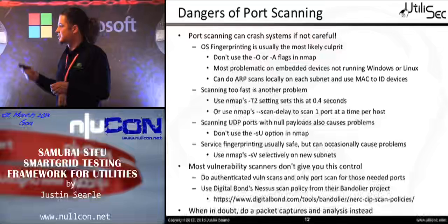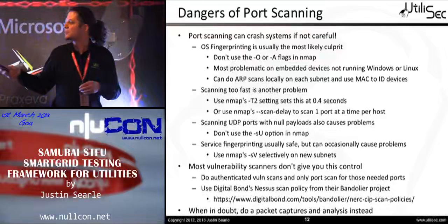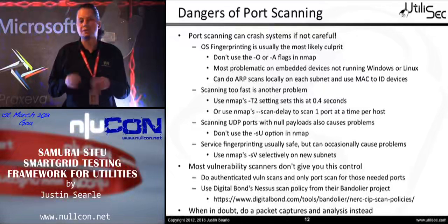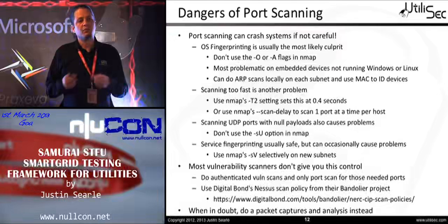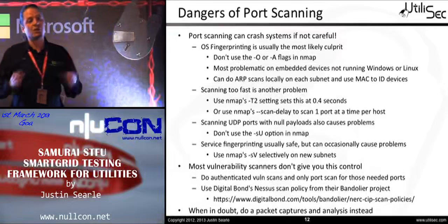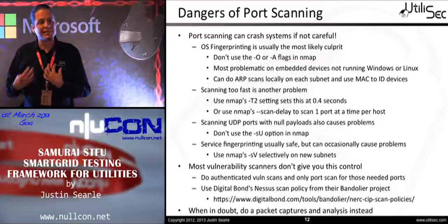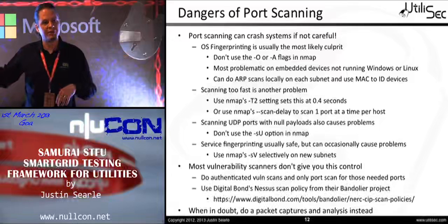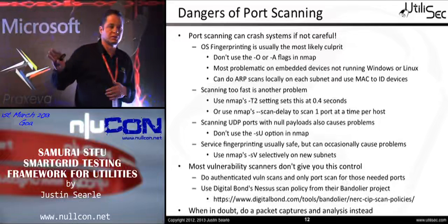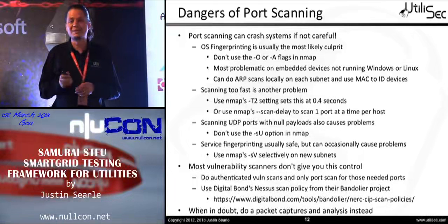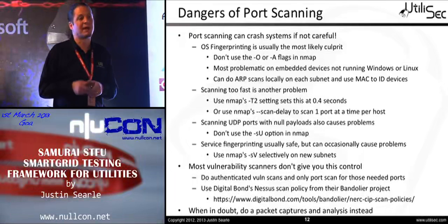Also, when you do things like vulnerability scans, having different tools like the Nessus scan policy from Digital Bond. Okay, this is a special policy for Nessus that you should use against any type of control system network. What it does is it tells Nessus not to do its normal tests trying to find vulnerabilities through unauthenticated means. It uses authentication inside of Nessus policies, disables most of the security checks that Nessus does, and tries to do everything through that authentication link. In the IT world, we see authenticated scans as a great capability, but we always see it as kind of half the picture. Well, what happens if there are more vulnerabilities you can't see authenticated? Okay, it gives us more information authenticated. But inside of the control center world, running unauthenticated scans and doing all the different checks is a sure way to crash multiple systems inside of the infrastructure. And sometimes not just crash, but permanently brick, requiring being sent back to the vendor themselves.